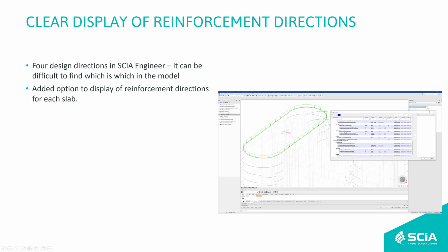So if you open the design default and change some directions, like I have here 45 degrees and 135 degrees on the lower surface for the lower layer, you can see here that this is direction 1, according to the 45 degrees to the x-axis, and then the second direction is 135 degrees. It's really clearly visible which direction is which.